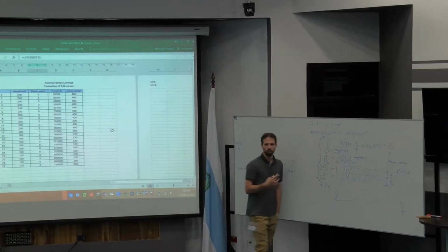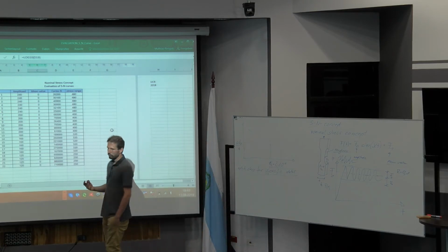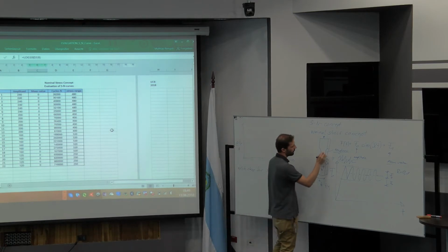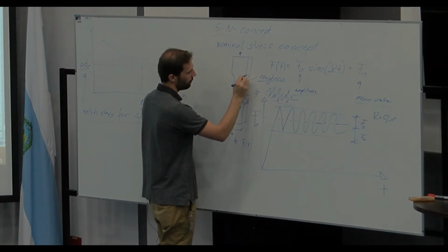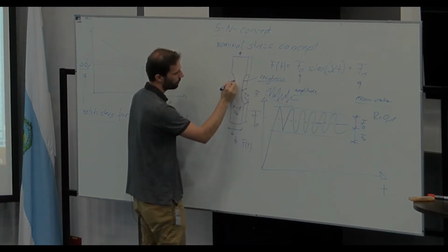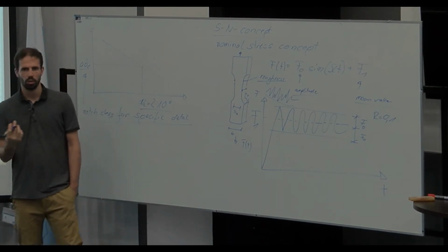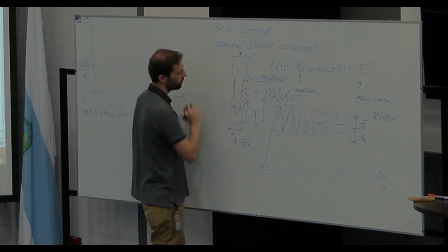So at this level, you also have to think about which roughness you want to have. Sometimes, due to the drilling or the milling, you can have here at the curvature some point of resting of the production machine. And if the production machine rests, you get here some notch.